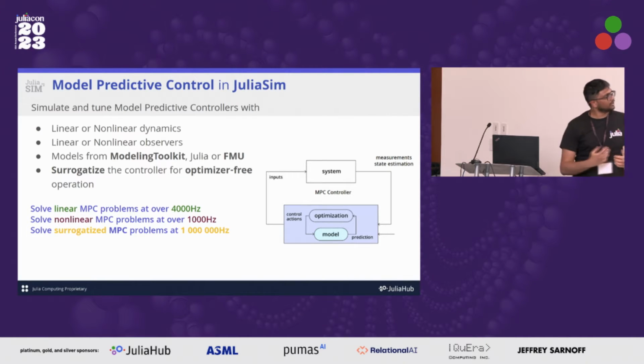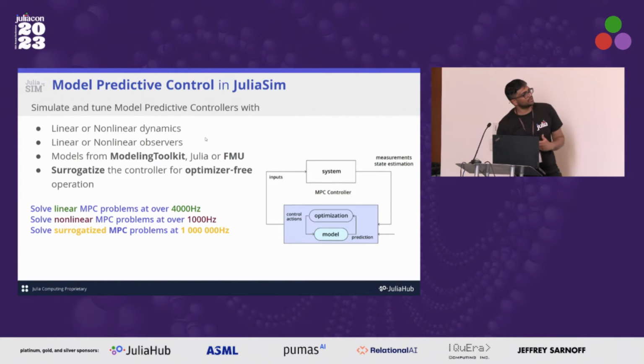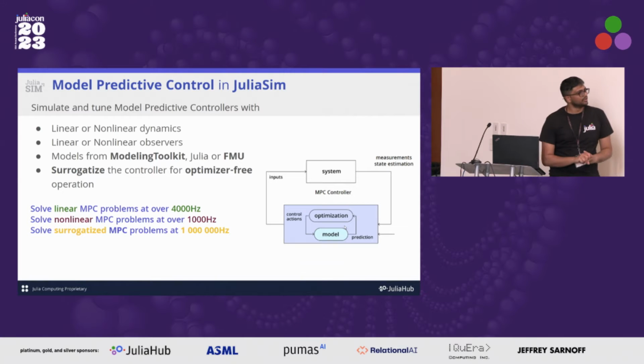So, how MPC works, I think of it as having three separate pieces. So you would have an optimization module over here. What that does is it simulates the dynamic model forward in time and then calculates the optimal control actions that would give you closest to your reference or closest to any objective you desire.